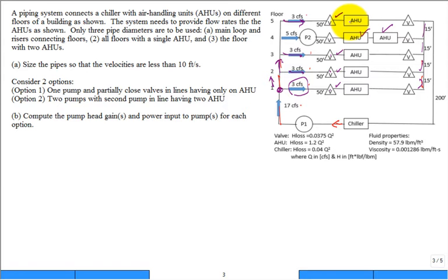Nope. You sure don't. So you have to find how much you close for 4 valves. For this valve, that valve, that valve, and that valve. That's not an easy task. But that's design option 1. You only have one main pump, and you use the 4 control valves to toggle it down. And you try to get it to be the minimum head that the pump puts in, so it's minimum flow.